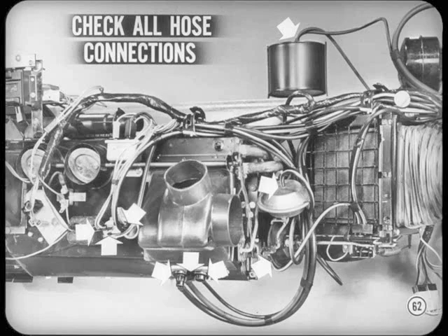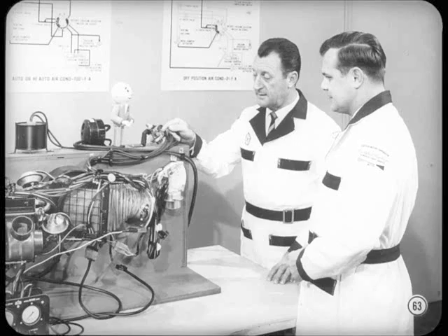The first thing I always look for is a pinched vacuum hose or a bad hose connection. In fact, I usually check them all out before I go through the sensor test. I've cut down a lot of lost time that way and avoided unnecessary control unit replacement. Another test comes early in my procedure, especially when the output air is too warm. When this happens, I have to take a look at the water valve operation.